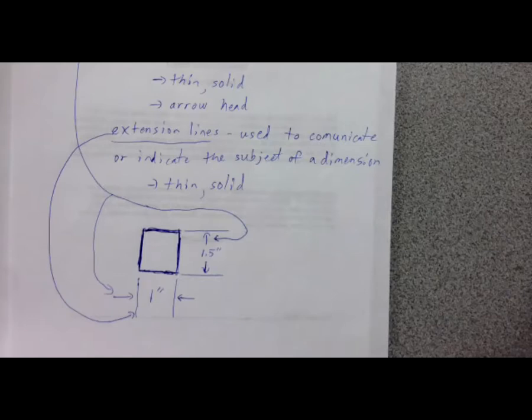No. Your visible lines and your hidden lines, you definitely want to make sure there's an obvious difference between those, which one's thick, which one's thin. Dimensions and extensions, it's normally pretty obvious what they are. But in general, try to stick with thin line types there. Other questions?